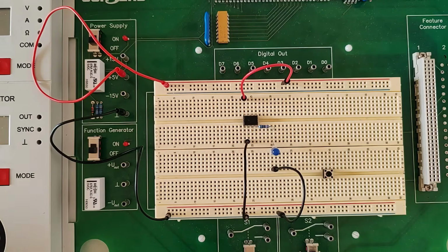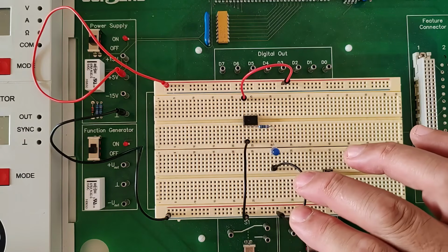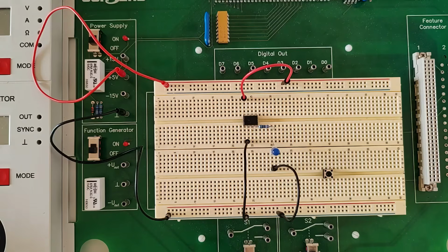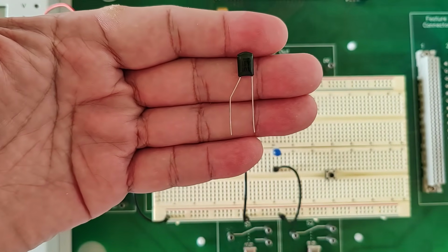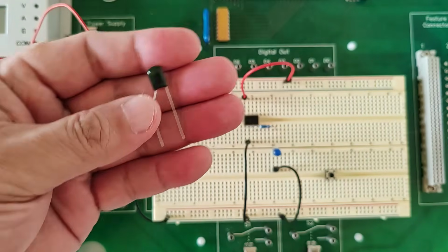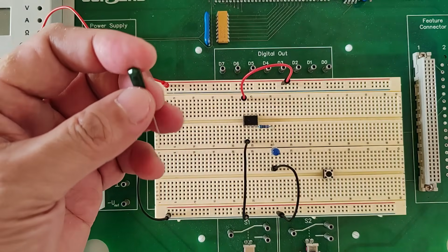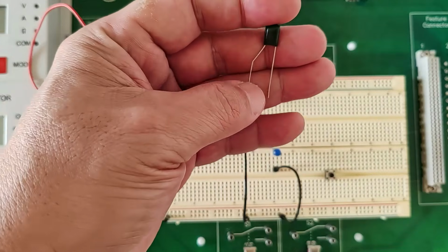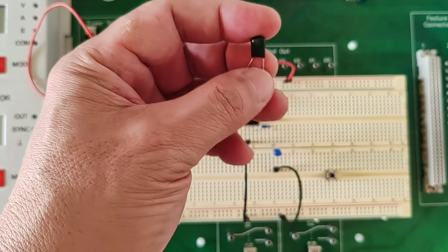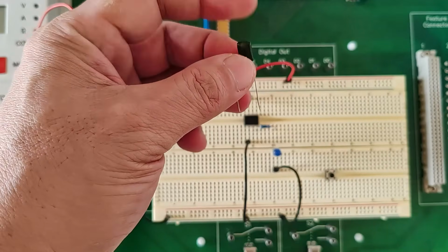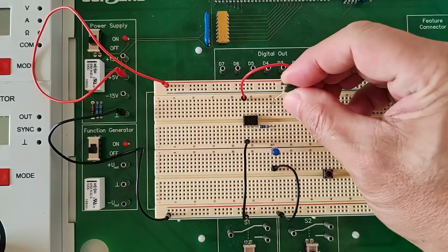Now, that's our output. In this particular circuit, the monostable multivibrator circuit, we are now using pin number 5, the control pin. Based on the schematic, we're using a 10 nanofarad capacitor. I have it here. Which terminal of the 10 nanofarad capacitor will be connected to pin number 5? We have to connect the positive terminal, the longer leg of this capacitor. The negative leg of the capacitor will have to be connected to ground. Let's do that now. So, 10 nanofarad capacitor connected to pin 5.